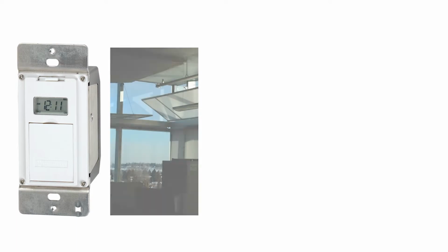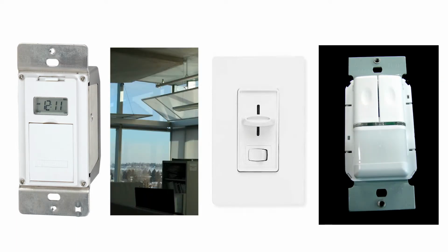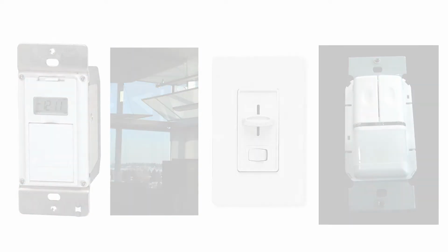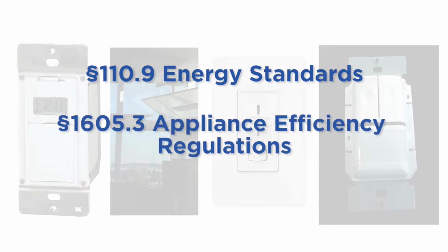Automatic time switch controls, daylighting controls, dimmers, and occupant sensing controls must meet mandatory device requirements contained in Section 110.9 of the Energy Standards, as well as requirements contained in Section 1605.3 of the Appliance Efficiency Regulations. Now let's introduce the 5 types of mandatory indoor lighting controls required under the Energy Standards. Outdoor controls will be discussed in Module 7 of this series.